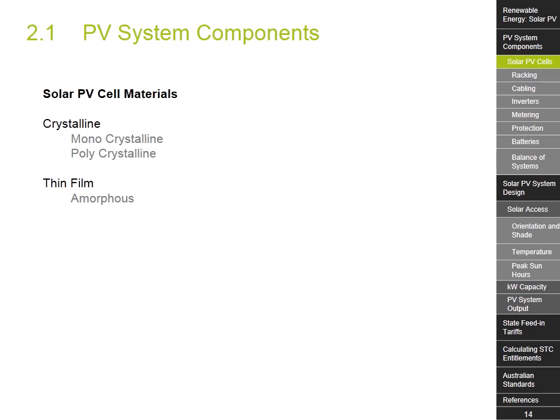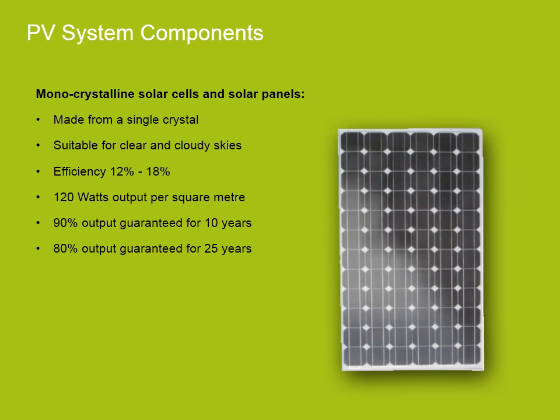The material that a solar cell is made from has a dramatic effect on energy generation, from the energy used in the manufacturing process to the energy produced by the cell. PV cells vary based on the crystallinity, band gap, absorption, and manufacturing complexity. Monocrystalline silicon cells get their name from the fact that the silicon wafer is cut from a single crystal of silicon. Silicon is grown in a laboratory and is then sliced thinly into wafers.